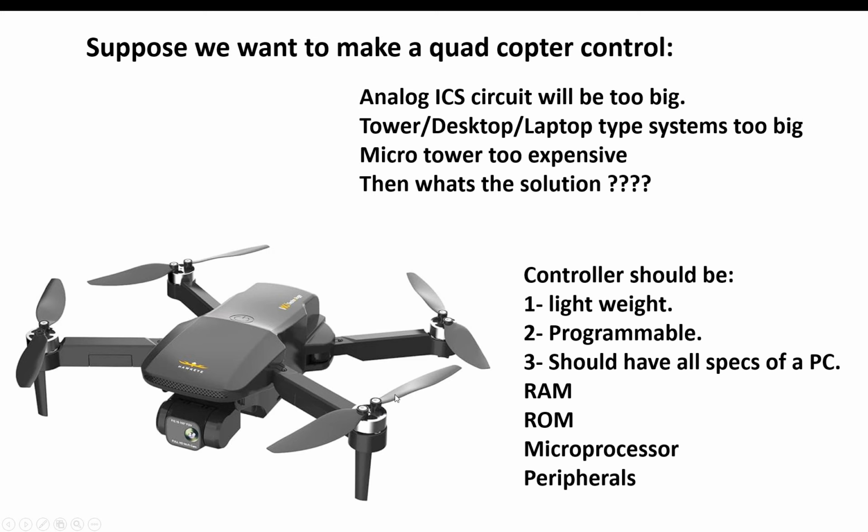Here the motors are peripheral devices, this camera is a peripheral device, the radio frequency module is a peripheral device. Whatever devices we have should be interfaceable using various ports like UART, I2C or SPI. Now these are our requirements. What can fulfill these requirements?